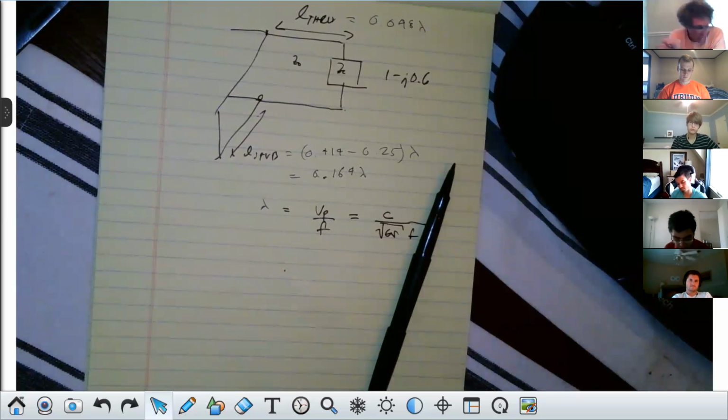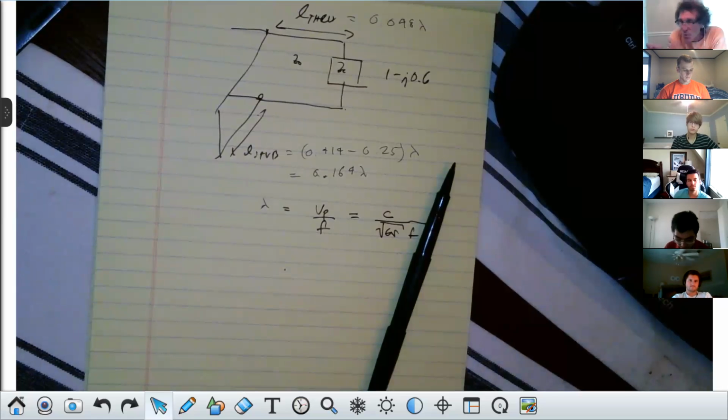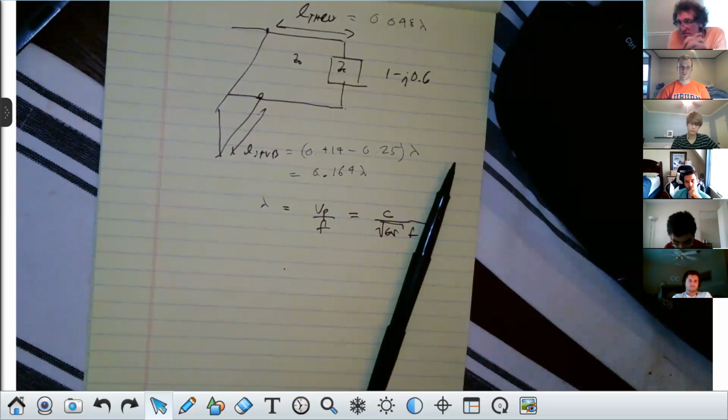If you just put 0.164, the default thing in that guy's mind is probably centimeters, and he'll assume that. You have to make sure you put the units down, either millimeters, centimeters, or something like this, because with designs like that, if you ship this stuff off, the people that do this usually are being paid by the hour, and they don't have a real vested interest to take a look and make sure it's right. They just fabricate something that comes back to you.